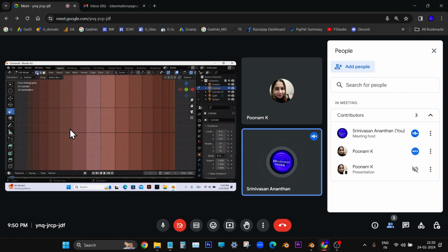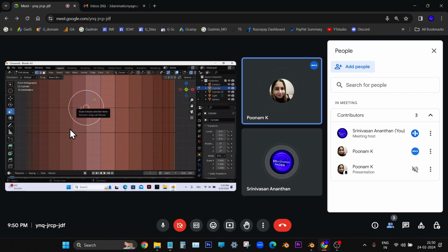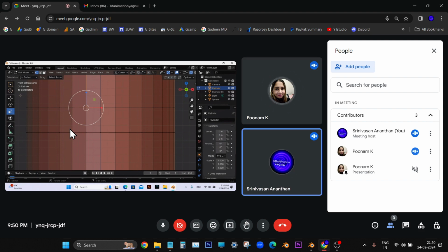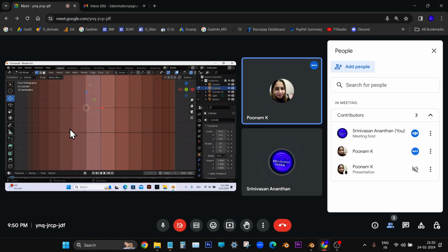Select one vertex, any one vertex, and go to the move handle in the toolbox and just move it and see. You see it moves freely, it is still separate. This is why I said it is not geometrically joined, it is still a separate object, or separate surface, separate faces.